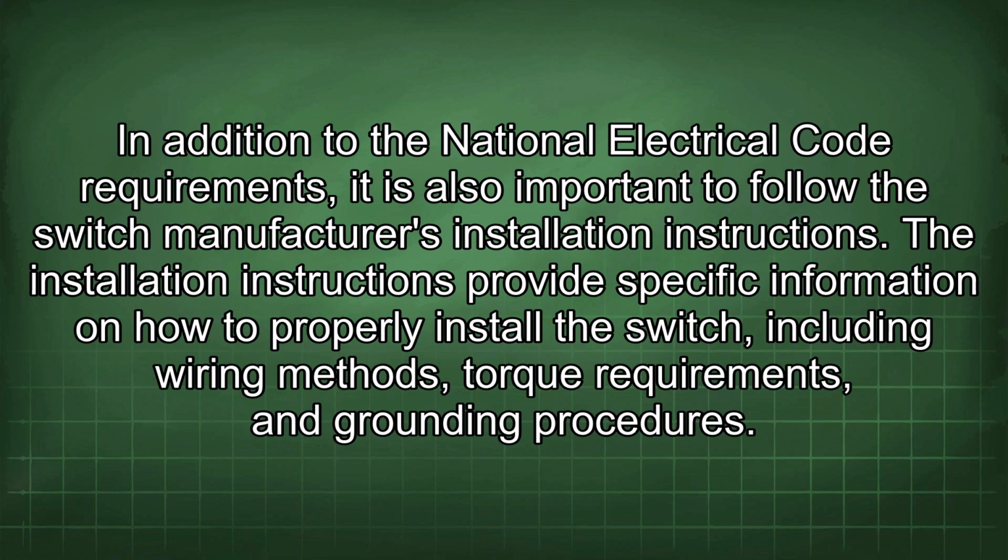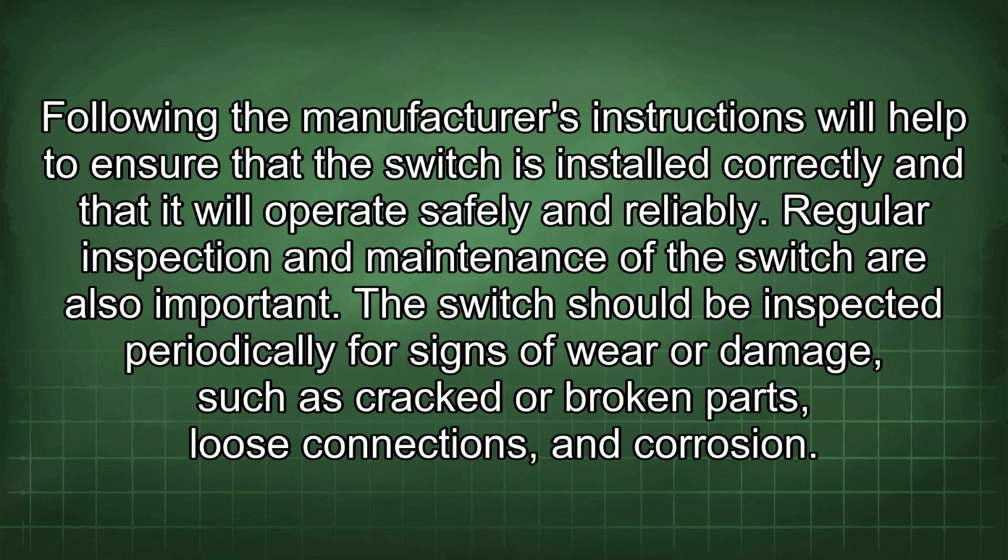In addition to the National Electrical Code requirements, it is also important to follow the switch manufacturer's installation instructions. The installation instructions provide specific information on how to properly install the switch, including wiring methods, torque requirements, and grounding procedures. Following the manufacturer's instructions will help to ensure that the switch is installed correctly and that it will operate safely and reliably.